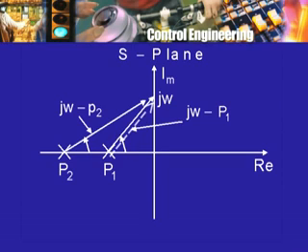So, we have the modulus of GH at j omega, that is the gain at any angular frequency omega, equal to A divided by the length of this vector multiplied by the length of this vector, that is the product of these two lengths dividing A. You remember in the root locus method we talked about distances to the poles and distances to the zeros. Here of course there is no zero, there are only distances to the poles. So, the gain equals A divided by the distance of this pole from j omega multiplied by the distance of this pole from j omega.